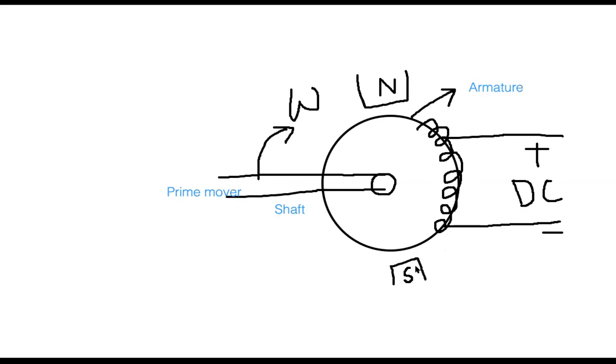So in that way, because the flux, this means North Pole and South Pole effect, is getting changed, consequently the voltage will build up on the coils, and then you will be getting the DC voltage here. So therefore, everybody keep in mind, in case of the DC generator, armature will rotate. Armature means coil will rotate, but the magnetic field will remain static. That is the key point.